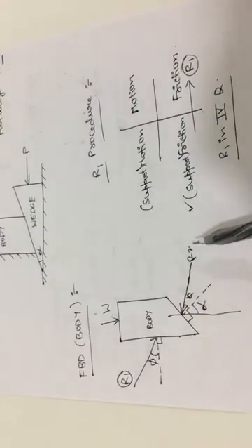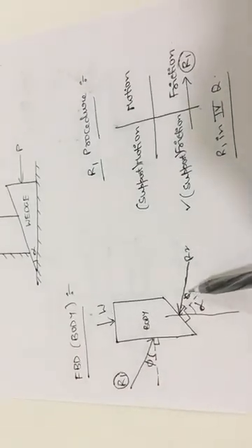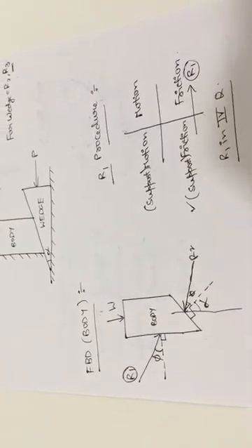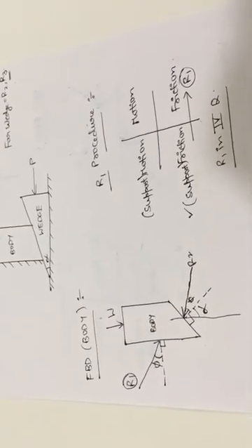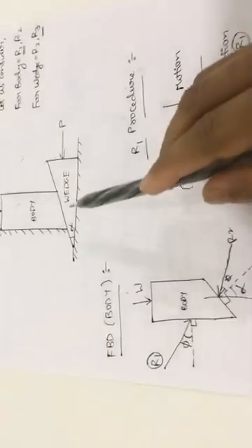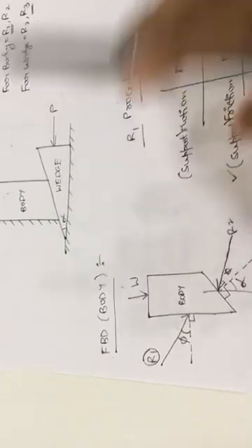you will get the reaction force R2 with some angle of the friction to the perpendicular of the surface of the contact. And remaining angle to the vertical direction y-axis is nothing but alpha. That alpha is coming from this angle of the inclination of the wedge only.